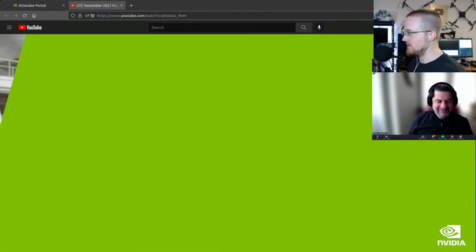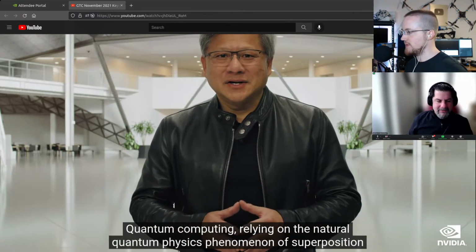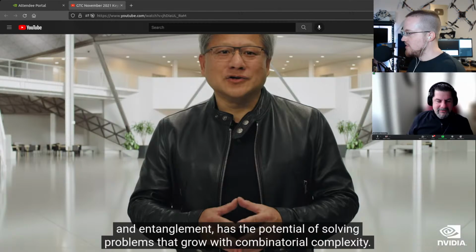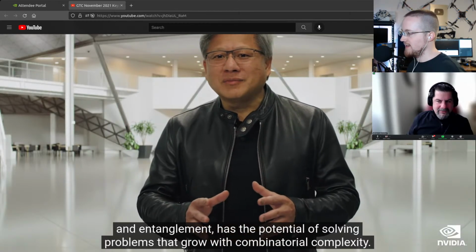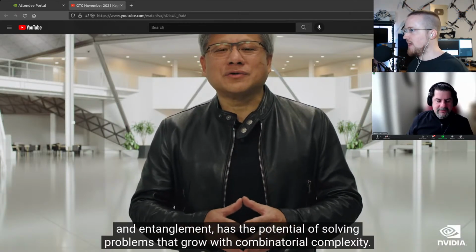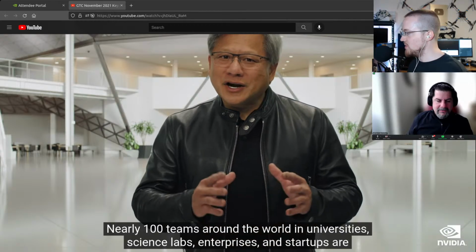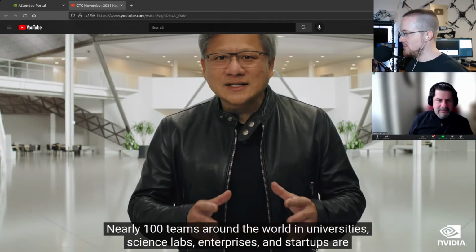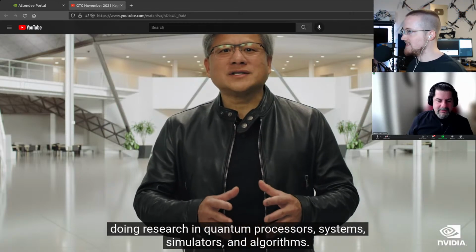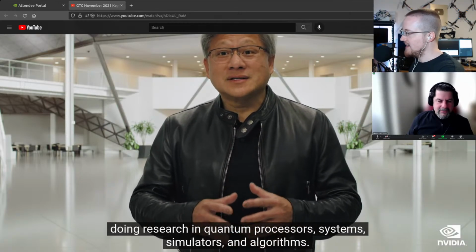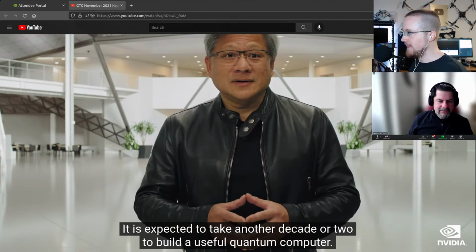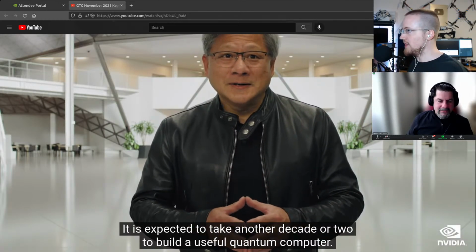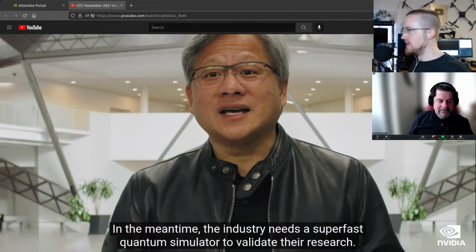So I was looking at all these other simulators, but with Omniverse, one of the things that's so easy is you have that URDF file that describes the robot, and then when I spend all this time creating the scene, I'm doing it manually. It's a bunch of drag and drop: you bring in a ground plane or some other asset, and then you save that as a USD file. I'm sure that concept is super common with something like Blender, but I don't know anything about Blender.